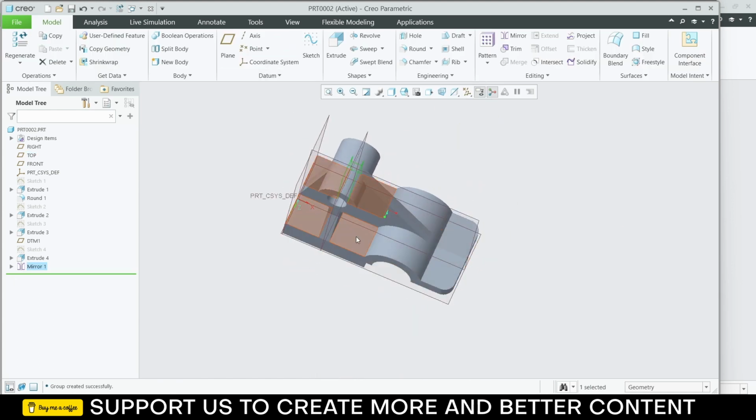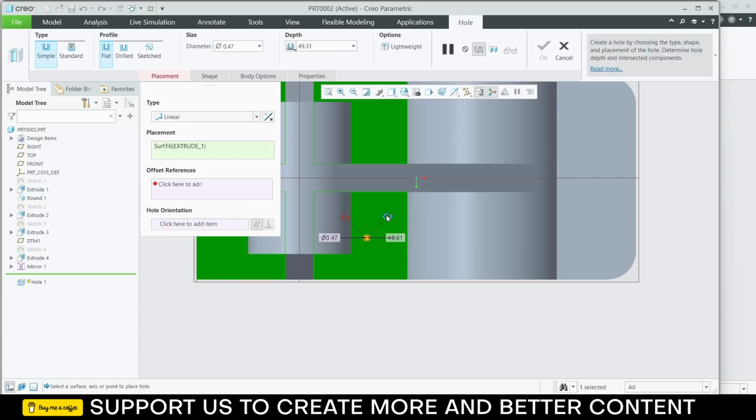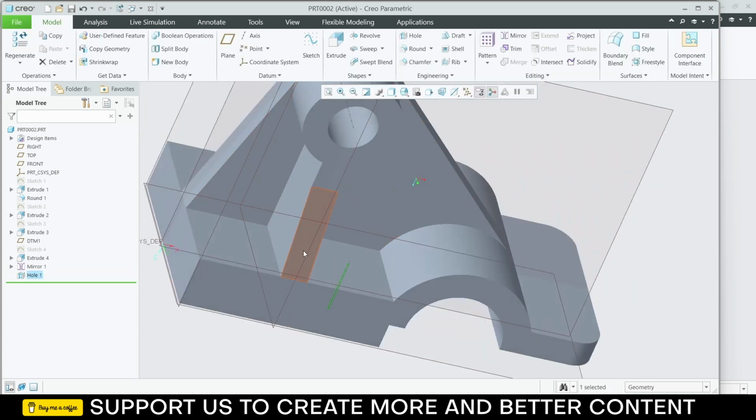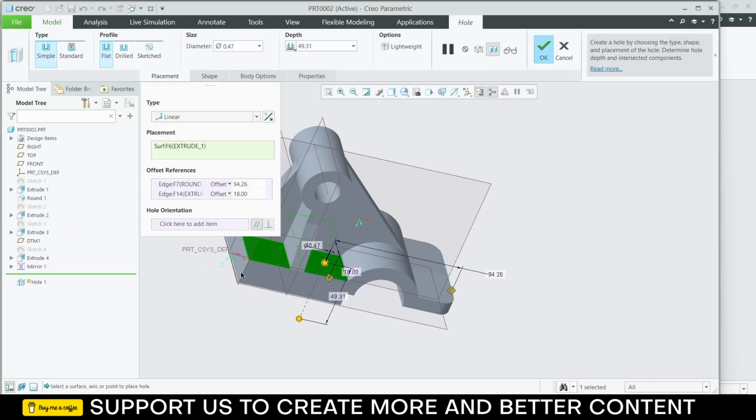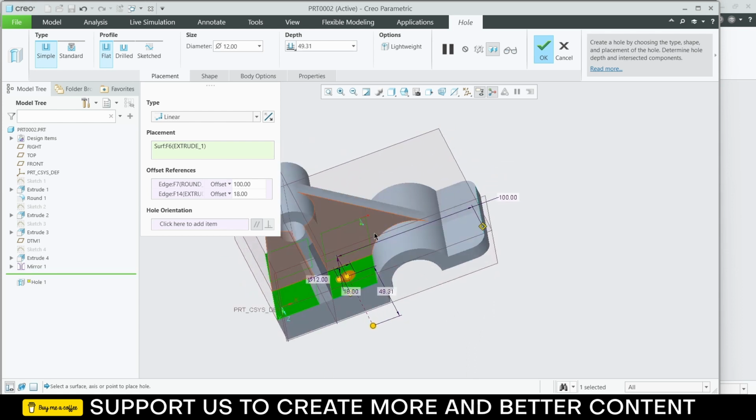Now I want to create some hole as well. So select this face. Click normal to the screen. Click on hole. Take them over to here and here. So this distance is 18. Oh, my bad. Click on edit. And this distance from here to here is 54 plus 46. The diameter is 12 and it will be throughout the hole.